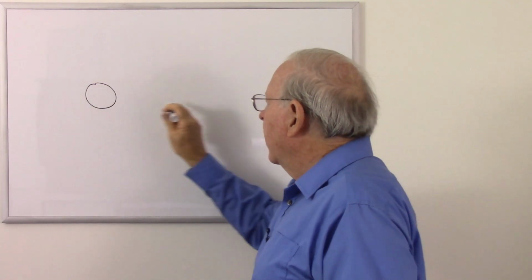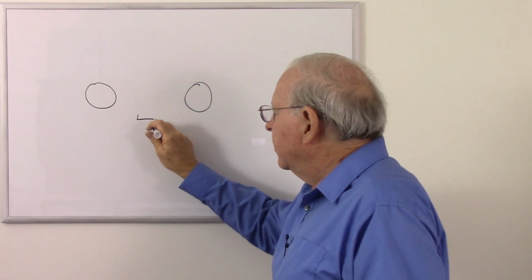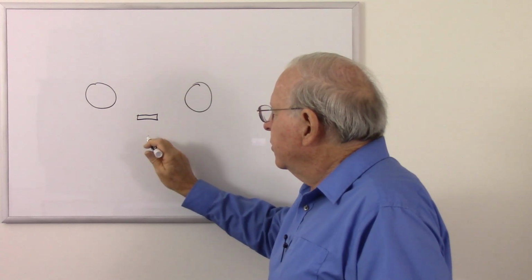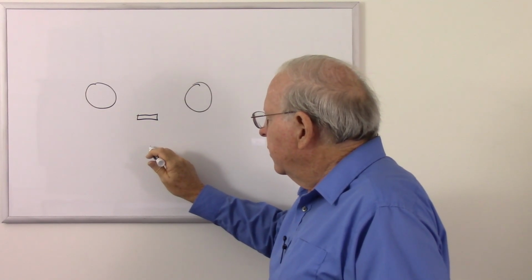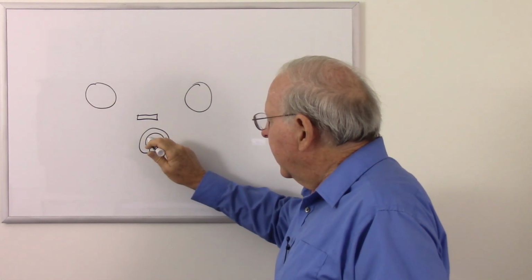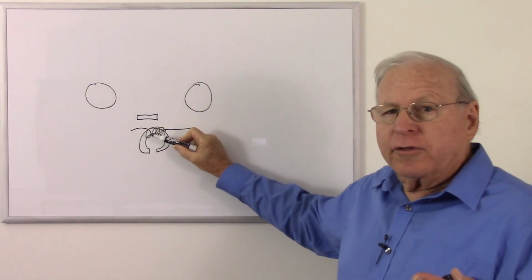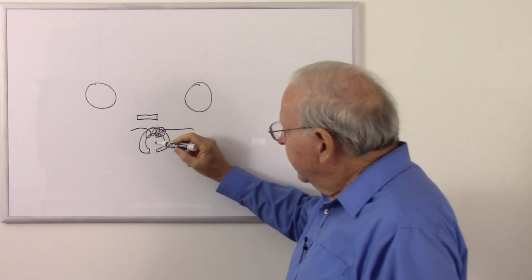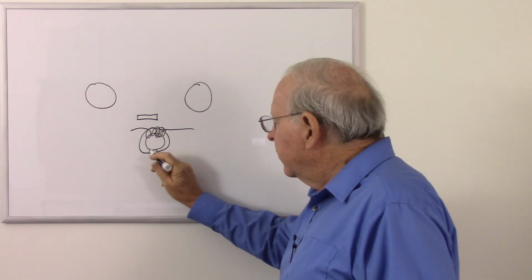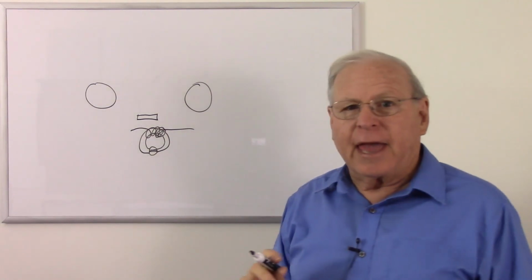So here's a spool of wire here and another spool of wire here, with motors to move those spools, and in the middle is a recording and playback head, as it's called. So in here we'll just draw it like this, a broken loop of iron which has wire wrapped around it. And of course, as we put current through this wire, what do we get? A magnetic field. That magnetic field will be concentrated in the iron and span this gap here, and of course, since we have a gap, that magnetic field is going to escape the gap a little bit.